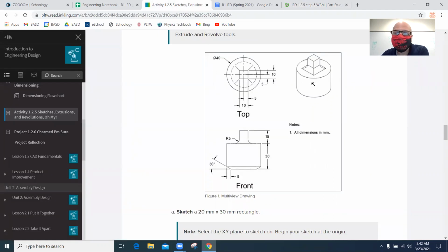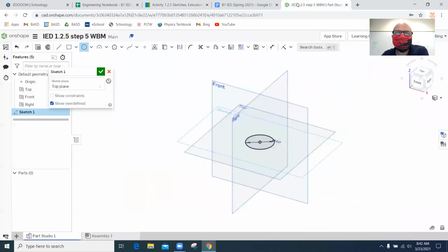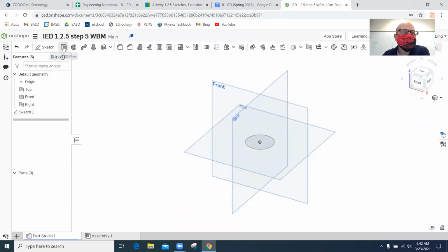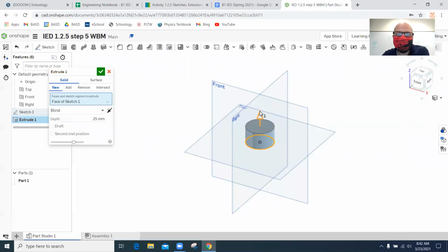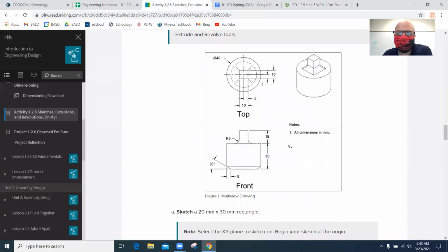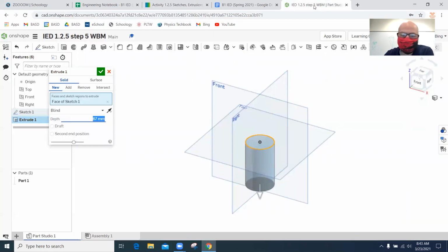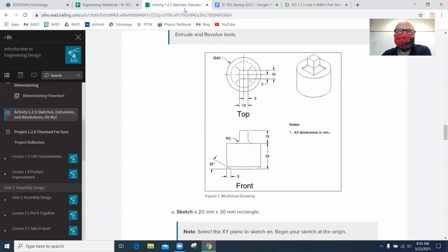And now I'm going to extrude it downward 30 millimeters. So what do I do? Check mark, meaning I'm done with the sketch. Extrude that shape. I like to extrude downward, at least, that's what my brain is processing. And down, what did it say, 30? 30, okay, that's good. Check mark, I suppose. Going back to this, what am I trying to do? I've got the 30 straight down, and then I want another thing on top.